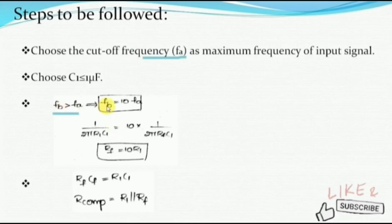For this we assume FB as 10 times FA. We know FB is 1 by 2 pi R1 C1 and FA is 1 by 2 pi RF C1. So 2 pi gets cancelled and C1 gets cancelled. Finally the RF value is equal to 10 times R1. From this we obtain the value of RF.